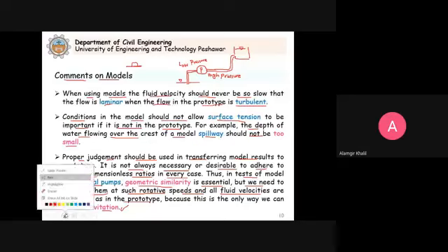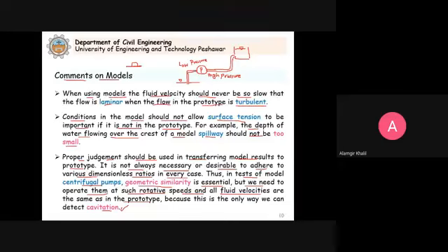Now this bubble, what will happen? Because this bubble developed here in the low pressure due to boiling of the fluid, now this bubble moves to the very high pressure zone. So this bubble will collapse, because now it moves to the high pressure zone. When it collapses, what will happen? The fluid from all directions, because it is a bubble, when it collapses, the high pressure fluid will move with very high pressure from all directions.